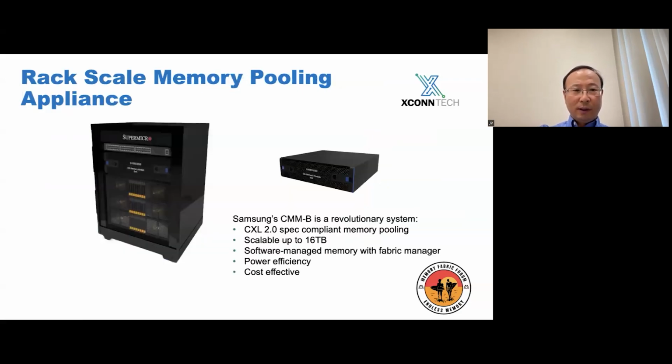Just an example would be the demo Samsung did at the March MemCon this year. This is a rack scale memory pooling system where there are 3 servers and 1 memory appliance, which Samsung called a CMM-B device. These servers connect to the memory box, which provides a large memory pool up to 16 terabytes.